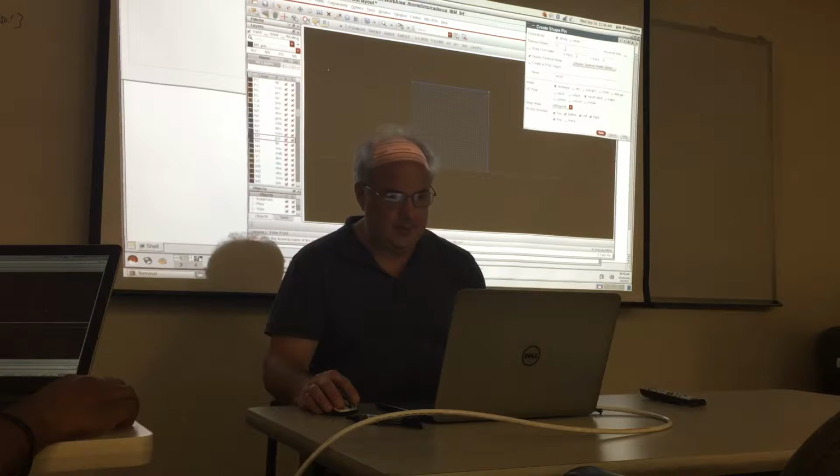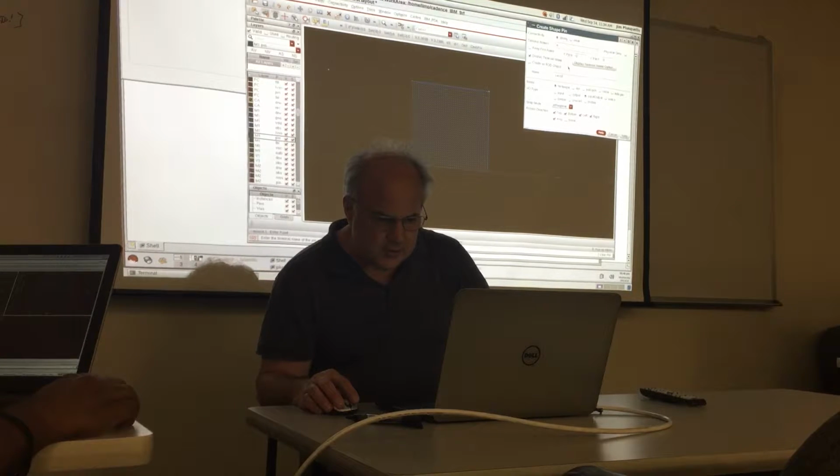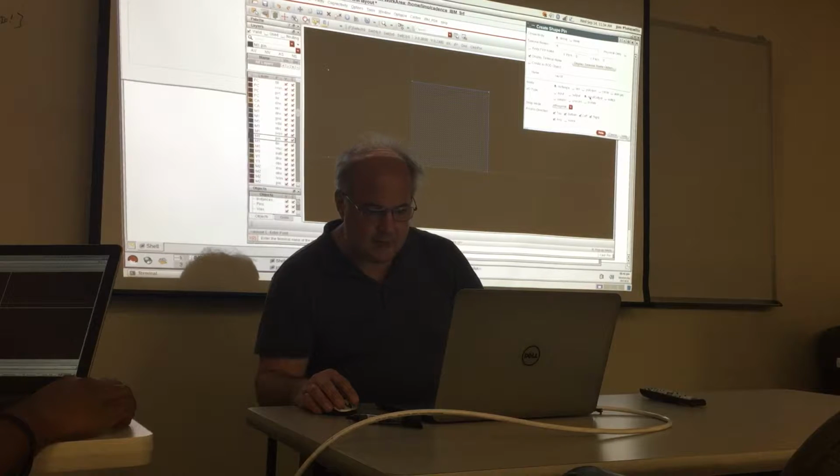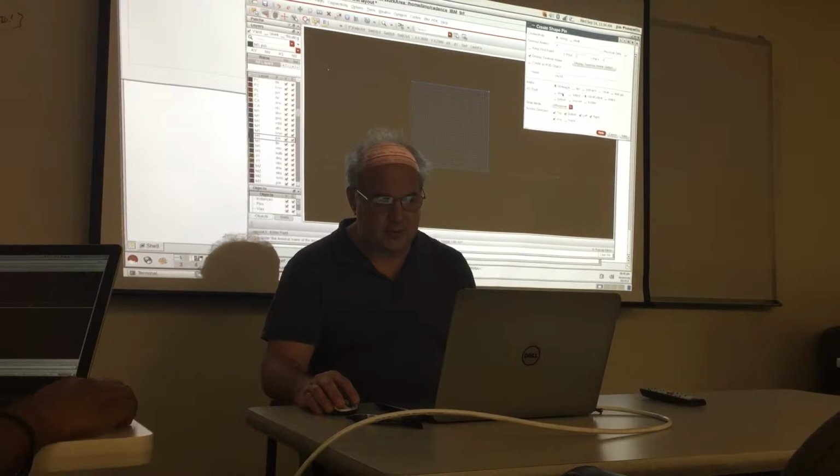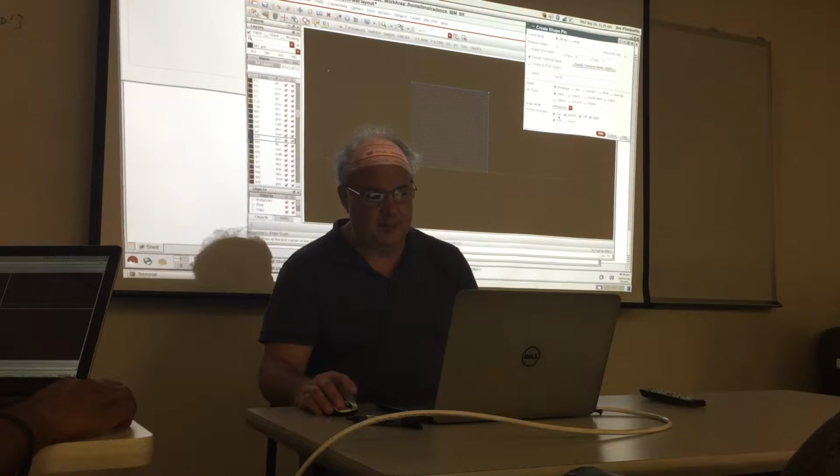Okay, and so you add your name up here, and there's usually a direction. It's in out by default, so you have to play with this. You can always edit it. I'll show you how to do that. Let's say that this is an input pin. You've got to mark it as input.